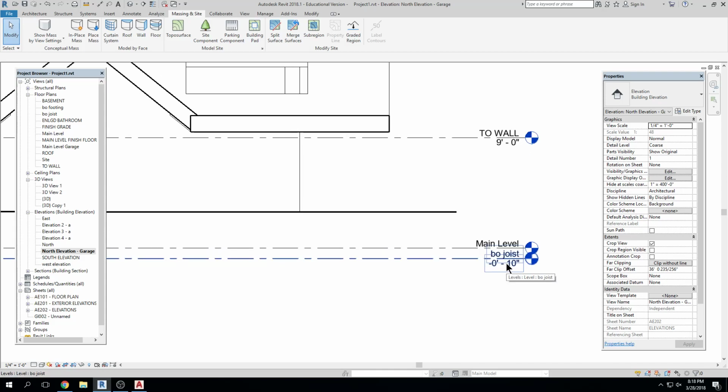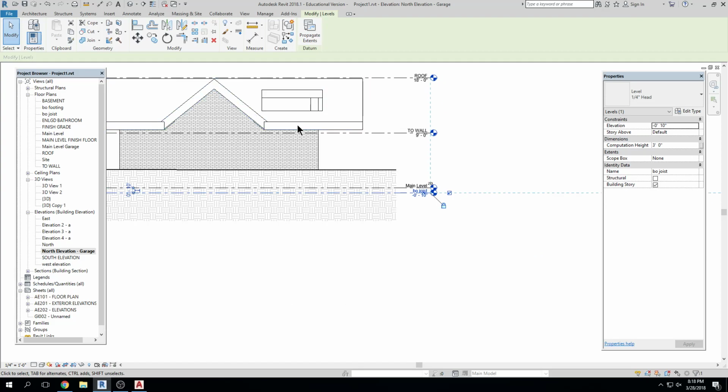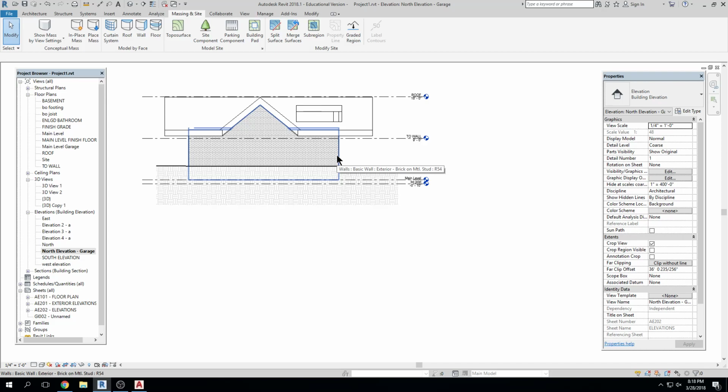Meaning that these levels tell me that when I created them, this one says 0, negative 10 inches. So that means that if there were a datum marker in Revit and we called it 0, the floor plan has been created at that level. It's not 100 feet above it. It's not 200 feet above it. It's not 4,800 feet above sea level. It's at 0, okay? So when I bring a topo surface into Revit, if it's at 4,000 feet above our datum marker 0, it's going to be 4,000 feet above our project, essentially.